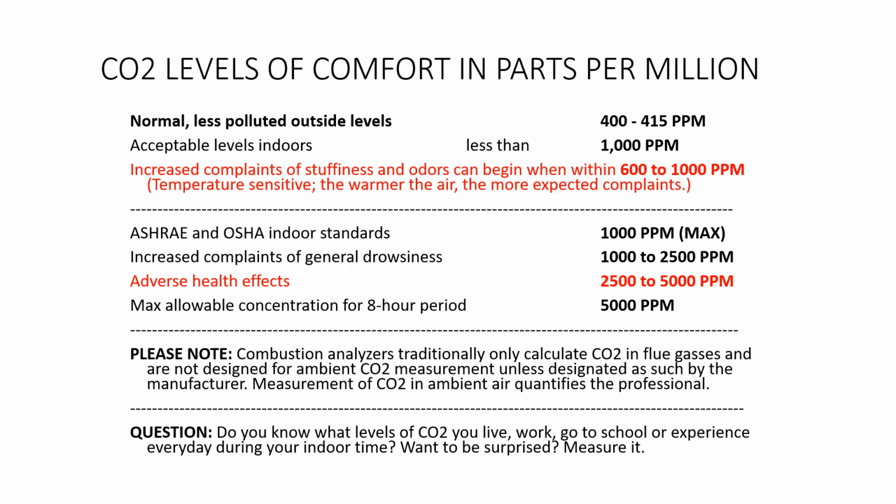Fresh air. We need clean, fresh air. We need oxygen. So what are the CO2 levels of comfort in parts per million? Well, you start getting increased complaints of stuffiness and odors between 600 and 1,000 parts per million, and that's generally temperature sensitive. The warmer the air, the more expected complaints.